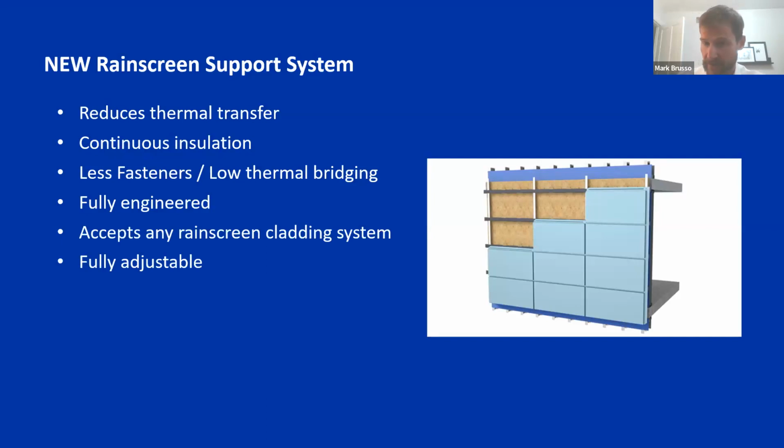There's a high level of adjustability with them, which is really important with regards to the trades that we're working with on the site. I always like to hear a few comments from the guys doing the install. So one of our products we also offer is a concealed lintel system with HB. And if we do any of those or we have those going out on site, I do like to hear what the bricklayers are saying about what their pain points are. And having something adjustable is really important on the job site because nothing is always perfectly square and perfectly built as per the drawings.